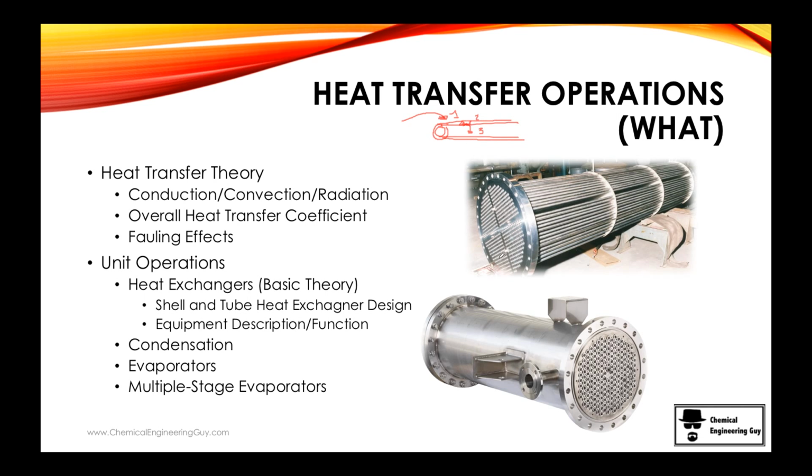But typically, especially when you're analyzing very huge heat exchangers and you just care about what's the heat exchange rate or the overall heat coefficient, you will want to have an average of these three guys right here, and we call this the overall heat transfer coefficient. And you can have an overall heat transfer coefficient for anything, actually, even also heat plates, whatever transfer media you may recall, you will have an overall heat transfer coefficient.